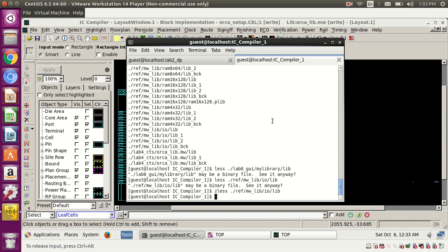Whenever there is a clock pulse, the PMOS and NMOS are going to switch on. So for some short time the PMOS and NMOS are both on, which means there is a short circuit current in the flop. We know that even in an inverter, for some time whenever the signal is rising through 0.5 volts, both transistors are on and some short-circuit current flows. So we are saving that much short-circuit current for those 10 clock cycles. Suppose we do that for 10 flops over 10 clock cycles, or for 10k cells, then we have saved a lot of power.